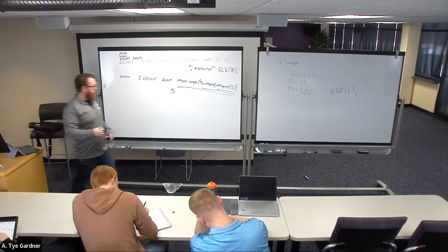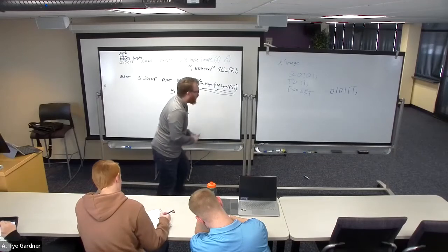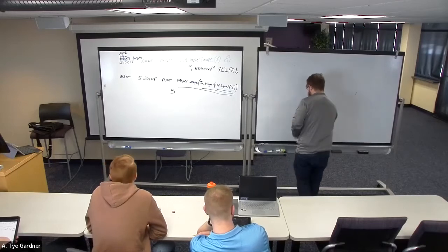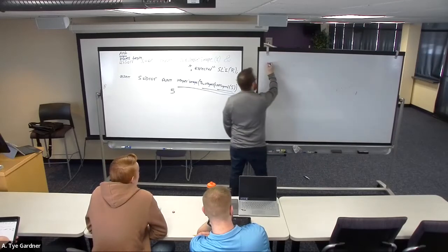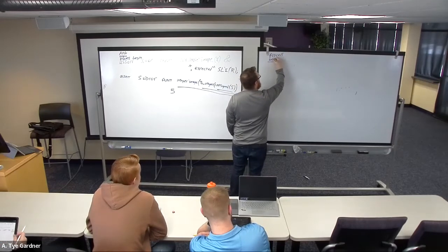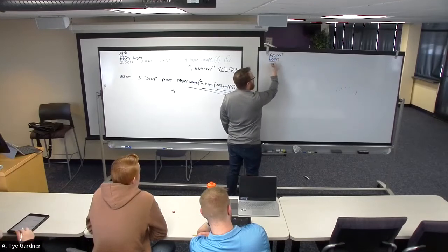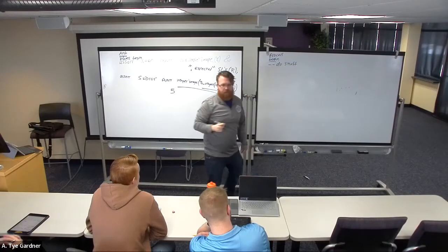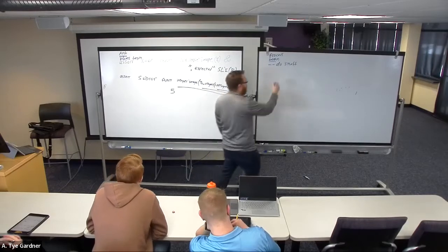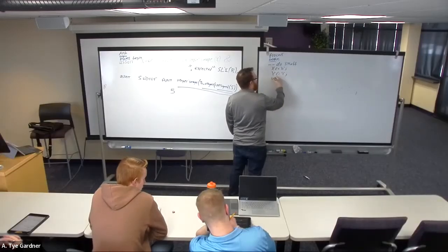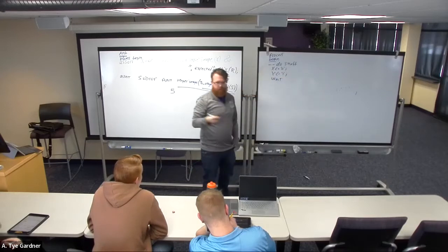Just like with our other test benches, where we basically do some form like this, process begin, and then inside of that we do stuff, right? Which is something like X gets assigned to 0, Y gets assigned to 1. Wait for some amount of time, right?